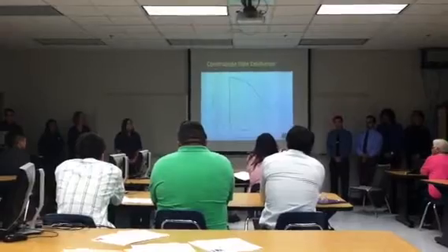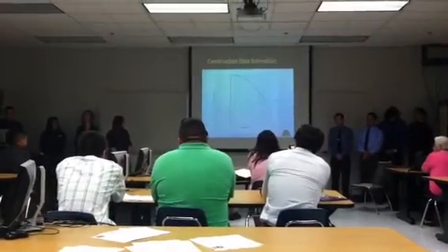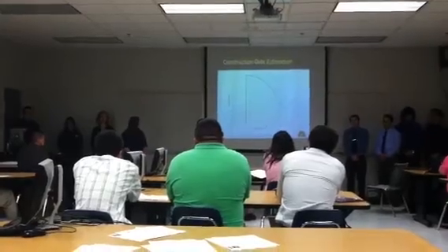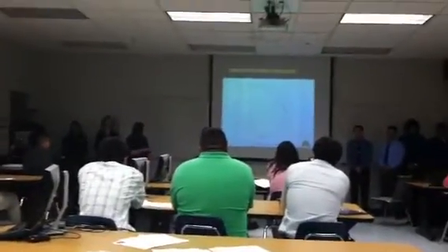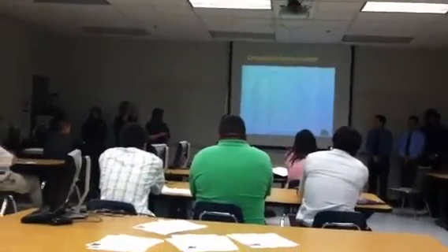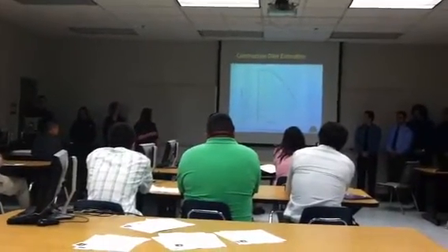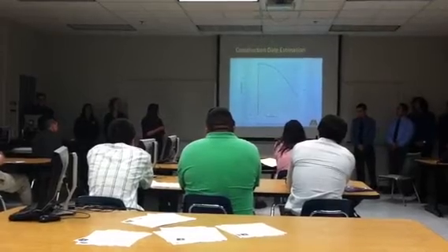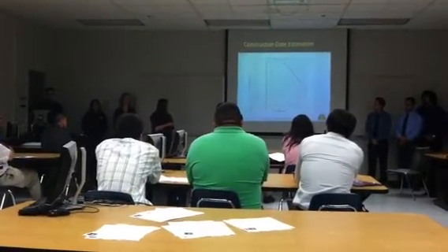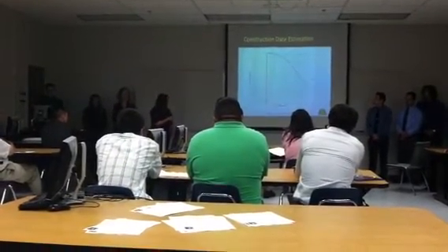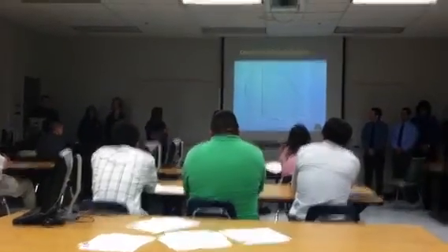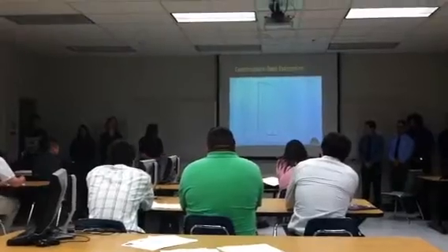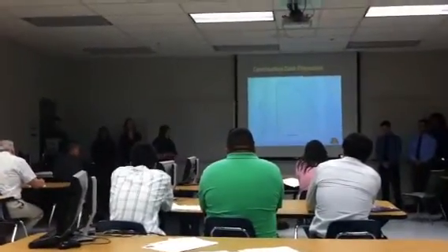When we were inputting data into MicroPAVER, we realized many of our construction dates were missing, so we decided to use the pavement life curve, which is this one right here. This is a best fit curve between 2 points. This point right here is the 2008 inspection date, and this point right here is the 2012 inspection date. When the curve hits the maximum PCI of 100, we move down to the x-axis to obtain the construction date that was missing.